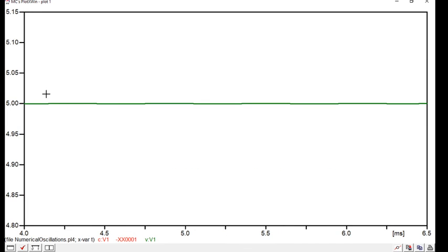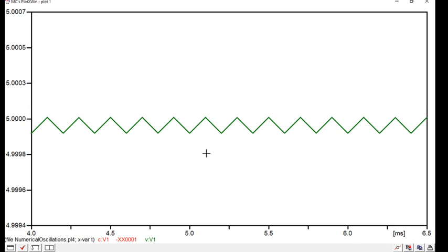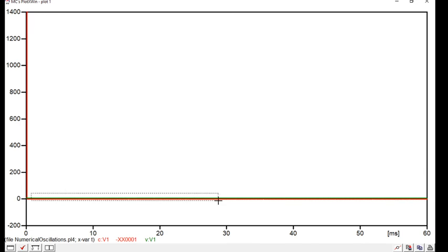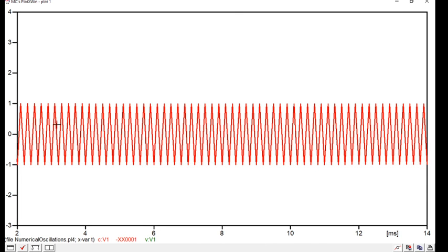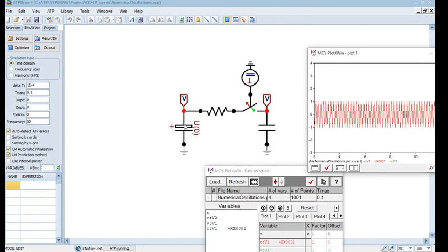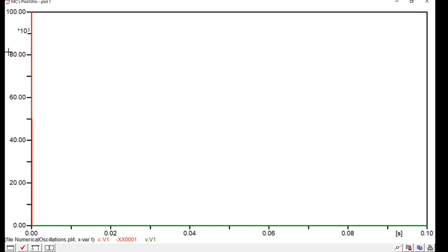See here, there is actually a chatter effect happening in the voltage depending on the value of R and the things we choose. But in the current, it's really visible here. Eventually, for this circuit, the current should have died down. It's a simple circuit: R is negligible and C with 10 volts gets connected to another capacitor of the same magnitude. So the current actually oscillates from 1 ampere to -1 and so on, and it continues forever.